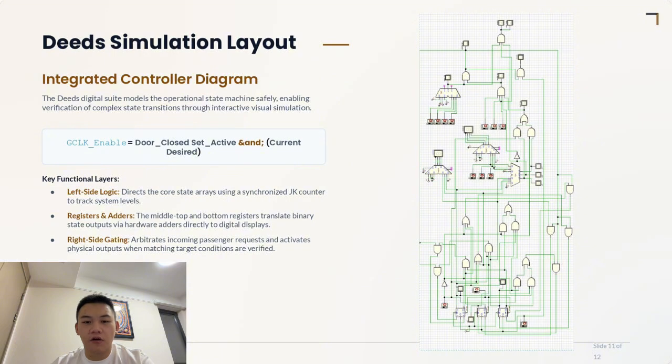During downward counting, the count sometimes skipped one floor because the clock signal was not stable. To solve this problem, we connected the manual clock directly to all 3 JK flip-flops. We then used the enable ADV signal to control the J and K inputs instead of controlling the clock.